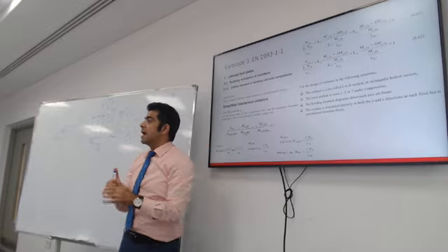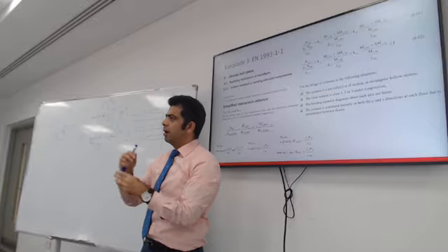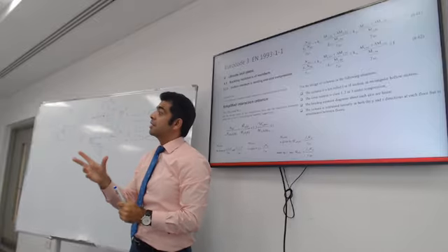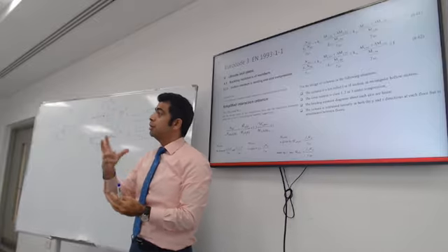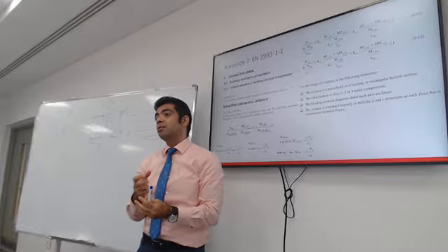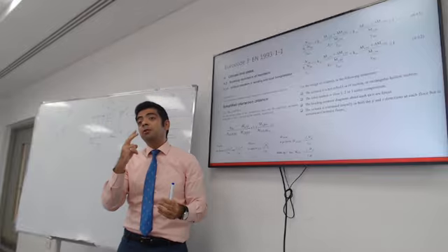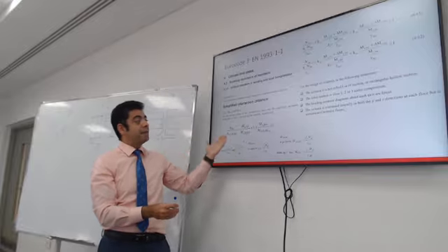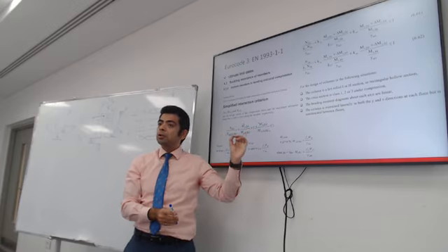So that means that each direction of action shouldn't exceed its capacity. Axial load shouldn't exceed the axial capacity of the column, same as moment in 2 directions, and you add them all together and make sure it doesn't exceed 1.